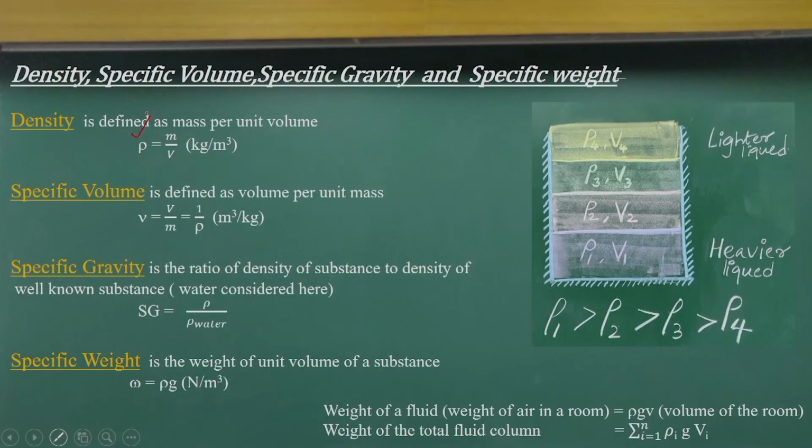So, that we can get in terms of kg. That means, if I take 1 cubic meter of water, the mass is 1000 kg, and that is the density for me, that means 1000 kg per cubic meter. So, the very basic thing is mass per unit volume, that is the density. I just re-emphasize that in any fluid flow problem, the foremost requirement is to calculate the mass of the fluid. So, if I know the volume of the fluid and the density, I can compute the mass.